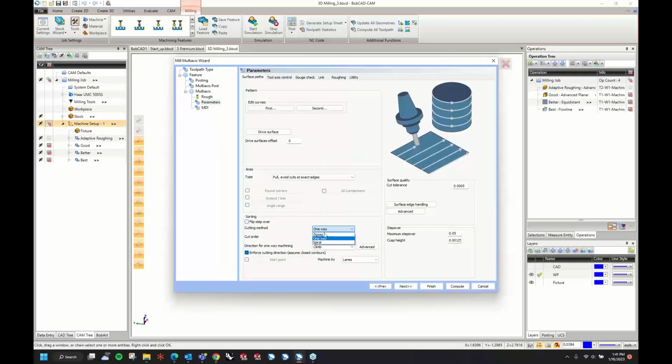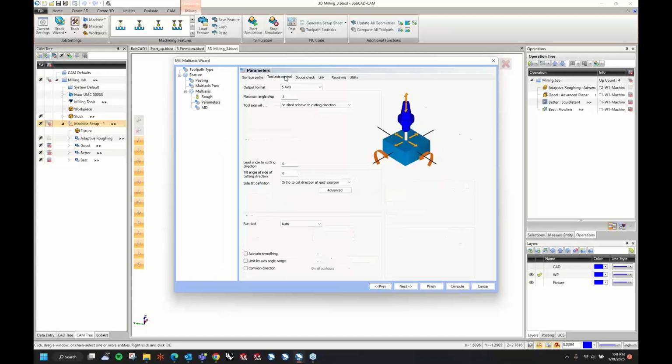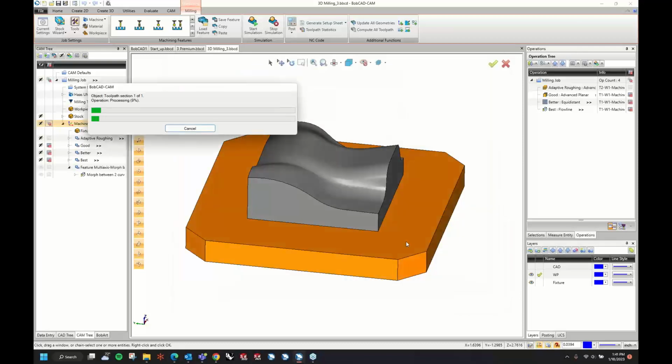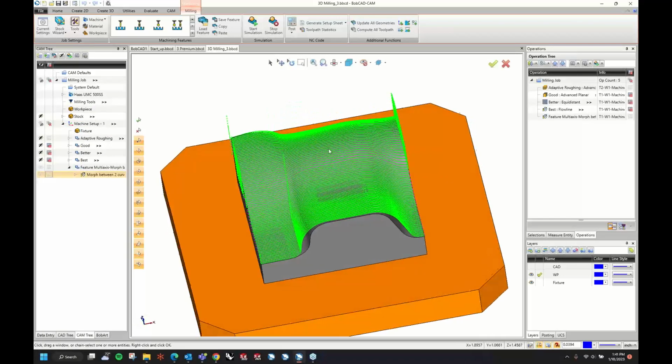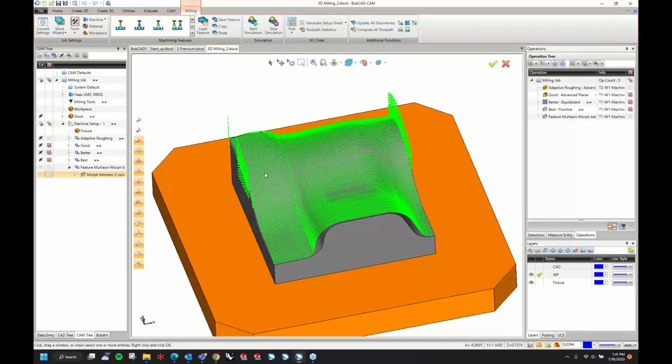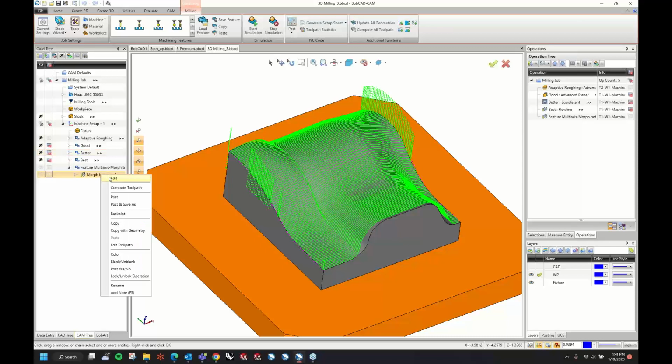now the flow line, you could do the same thing. And I'll leave the 50 thou max and 3 axis. But I can control it, have it go this way across if I want, or if I change my drive curves, or my edges, I can go the opposite direction. Let's change that retract.